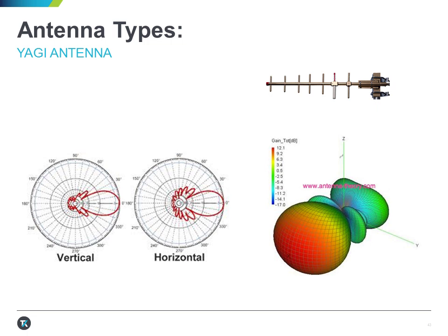So when we think about using a multi-band log periodic versus a Yagi antenna, the multi-band log periodic will be able to operate over a much broader frequency range. It's not uncommon for it to be able to operate over hundreds of megahertz. A Yagi antenna, by comparison, may only be able to operate over 50 to 100 megahertz. But the directivity of the Yagi antenna is much better, meaning we get a much sharper peak when we start using it for direction finding purposes.